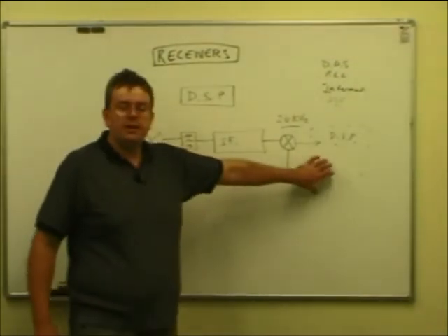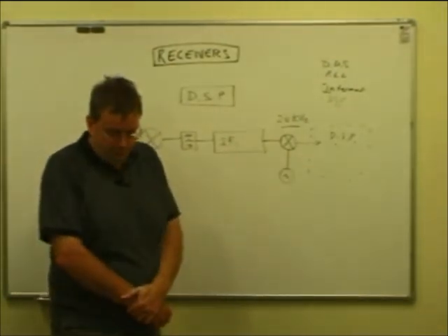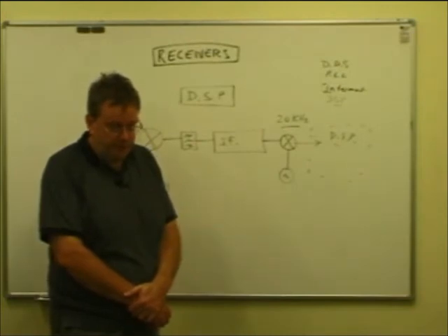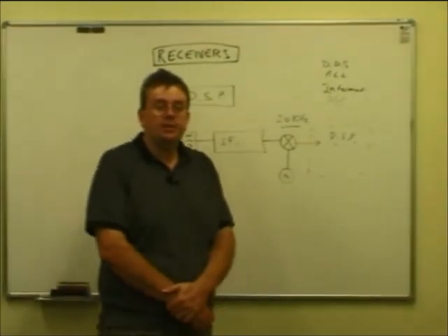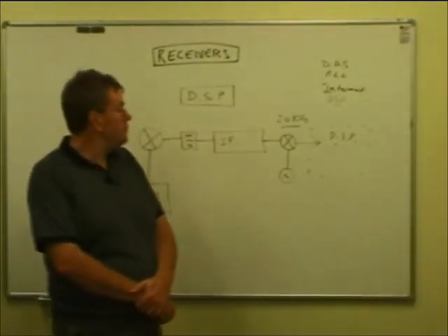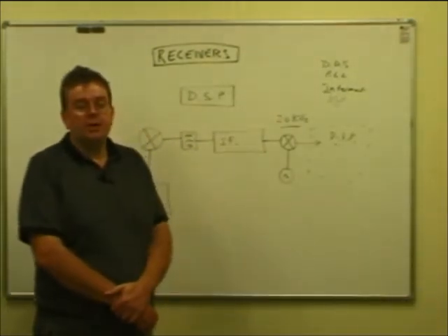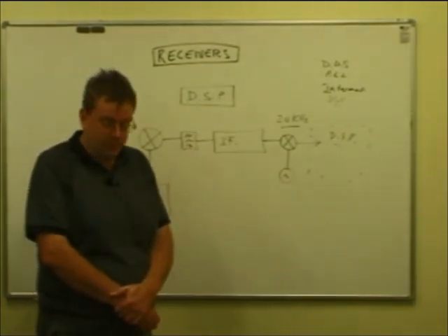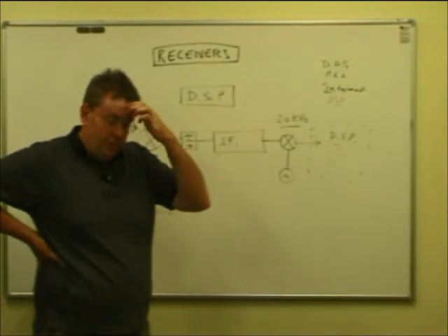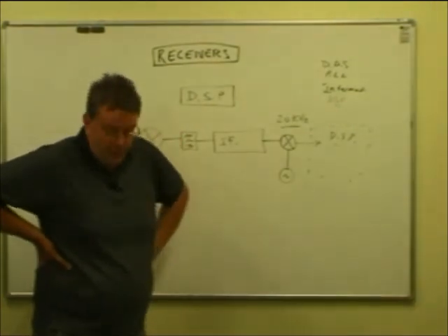This can actually be done on the sound card of a PC. You can take the sound out of your audio jack, out of your radio, and feed it into a sound card and run the appropriate software for getting rid of noise and doing DSP that way. And the other trick is with certain data modes, the information can be extracted off the signal using digital signal processing in the sound card of your personal computer. It's become a very powerful tool nowadays for people experimenting with that sort of thing.